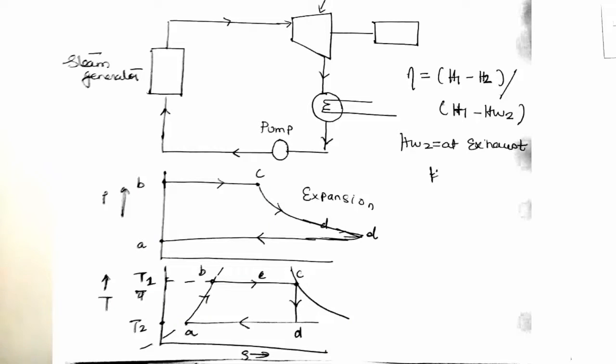And if you see the two graphs, you can see that from A to B the pressure has increased. And if you see the temperature graph, again during that same time A to B you increase the temperature. So this is what is happening in the generator. You increase the temperature and pressure, and again you are supplying that at C to the turbine blades, and there's an expansion happening. So the pressure is reduced as it acts over the turbine blades, as you can see in the graph, and then it is cooled down and transferred back to the steam generator again at a lower temperature.